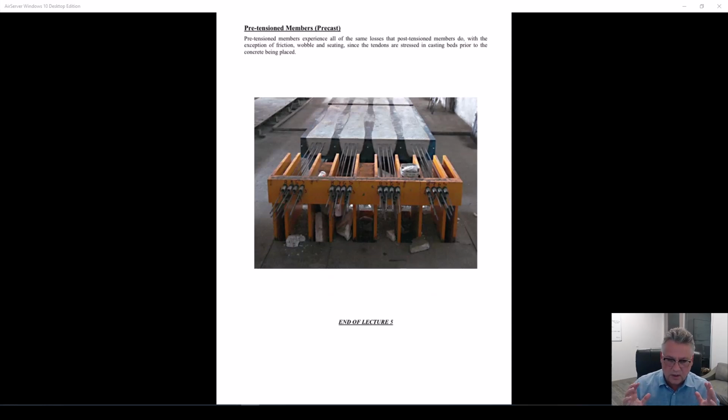But I want you to think in bigger terms. I want you to ask yourself why the 2 things that I give you to do, the decrease in drape, decrease in balance load, and then secondly, the reduction in number of tendons, why do both of those actually solve the problem? And remember, it's decreasing. We didn't add anything. We didn't add any cost. We didn't charge ahead like most engineers will do and start adding more force. We're smarter about it. Hopefully, you're leaving this homework assignment understanding a lot more about pre-stressed concrete.